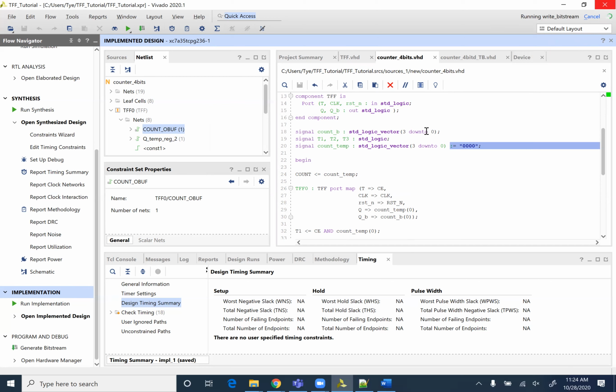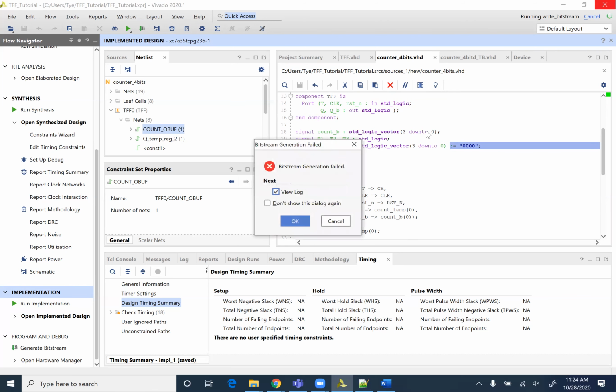Okay, so the first way is the way we did in class, where you wrote the bitstream and it programmed the board. But you'd notice if you turn the board off and turn the board back on, it's back to its default state. It is possible, and I don't do it in this class or the other one because it's inconvenient to me, but it is possible to write it into a memory that it automatically boots from on power up. On the board? On the board.